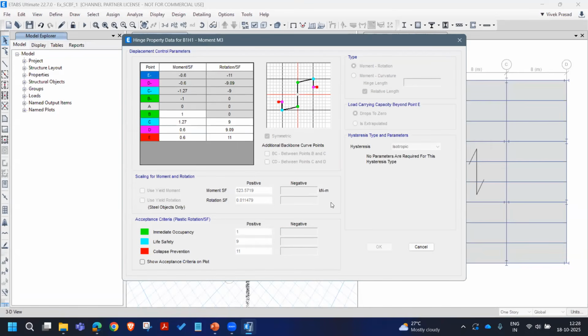So program is capable of doing the performance-based design for that requirement. Performance criteria can be set, acceptance criteria using this, which can also be displayed here. But we will skip that, but let's focus only on this part. When this is the yielding point and any member yields beyond this point will be displayed graphically, as well as other outputs are also available for that information in a tabular format. All right.